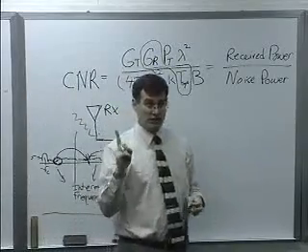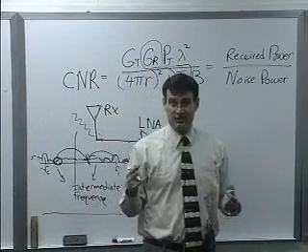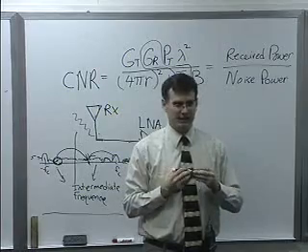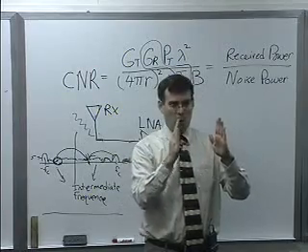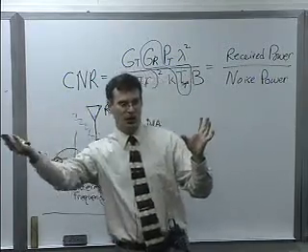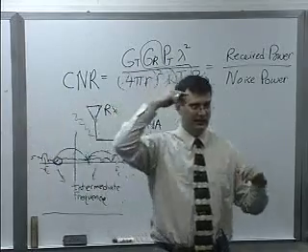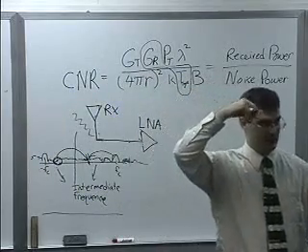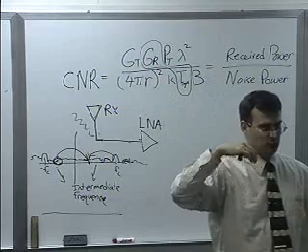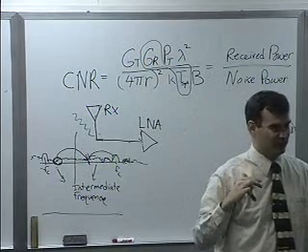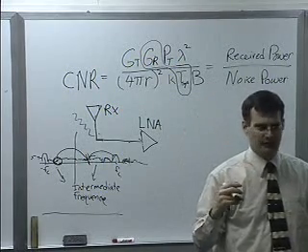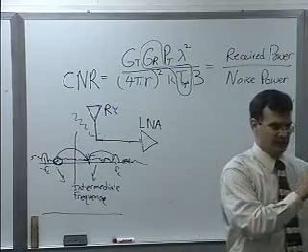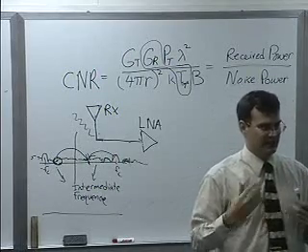So one of the tricks to picking out a local oscillator frequency is trying to pick one such that there's a quiet band that same distance away on the other side of the frequency spike in the frequency domain. So like if you're mixing 12 gigahertz down with a 10 gigahertz LO, we'll make sure that there's nothing at like 8 gigahertz that will mix into the band, that it's relatively quiet.